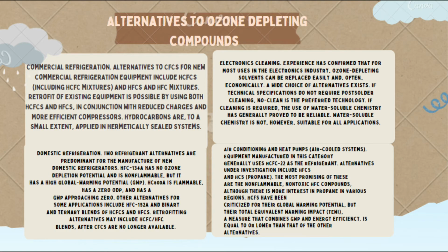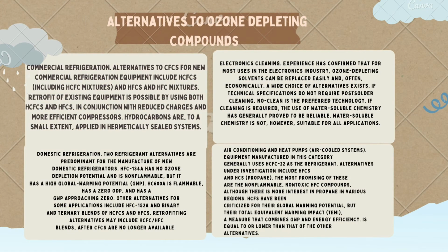Electronics cleaning experience has confirmed that for most uses in the electronics industry, ozone-depleting solvents can be replaced easily and often economically. A wide choice of alternatives exists. If technical specifications do not require post-solder cleaning, no-clean is the preferred technology.